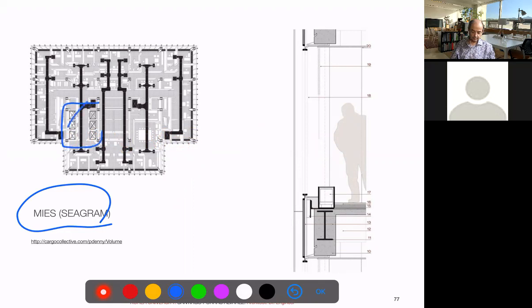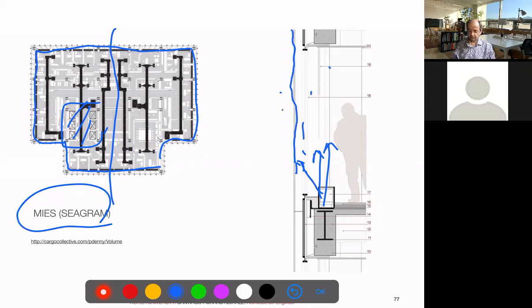Well, it has a side core, right? But you see the system is divided into parts, it's symmetrical, and it has a big effort on having most of the air coming through the facade. So it's kind of diffusers at a low speed, which regulate temperature in the most complex part. So it's where you have most of the heat or most of the cold in winter. So you have kind of air curtain, which then is collected through these return ducts and taken in just two complexes, right? So this is okay. And of course, the diffusers are thought to be distributed more or less regularly in the ceiling without disturbing the design.